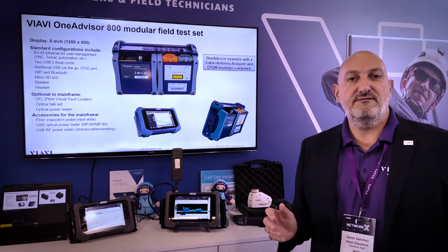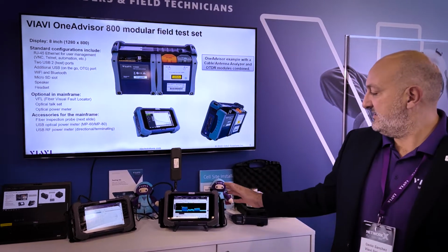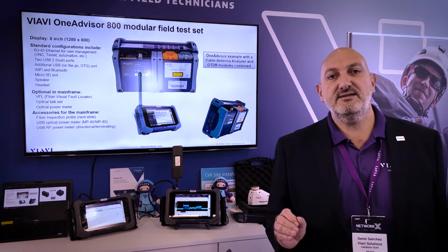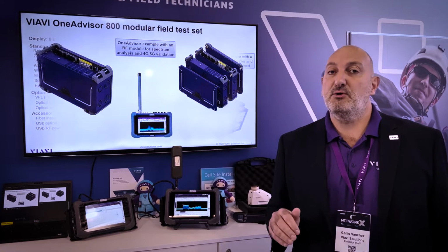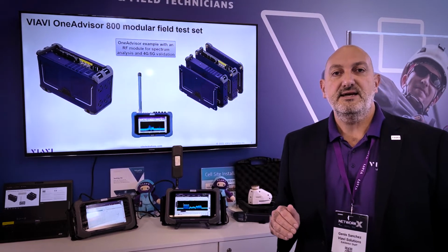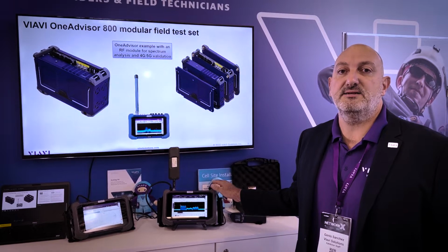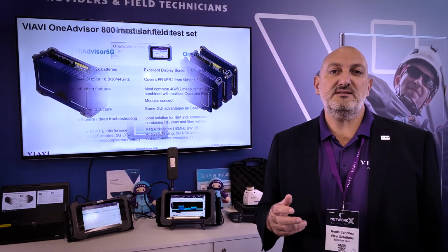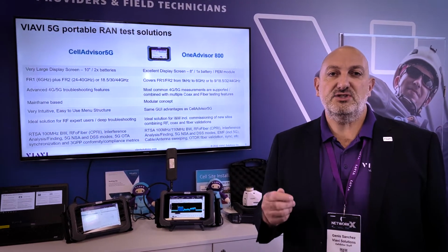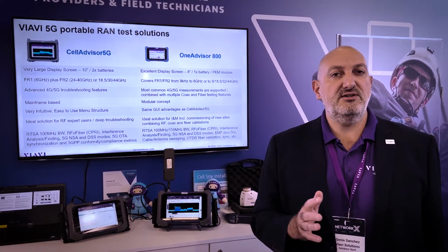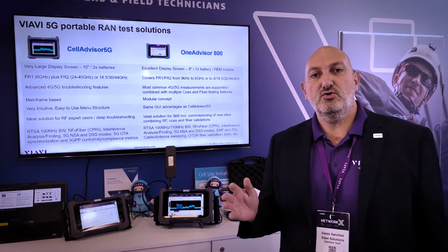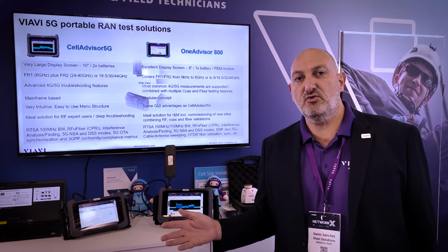For example, for external interference, the tool comes with a very neat real-time spectrum analyzer, among other interference analysis capabilities. This is a 110 megahertz analysis bandwidth real-time spectrum analyzer, and it allows you to immediately capture and identify those spurious signals, those leaks, those external interferences that are very difficult to observe otherwise with traditional tools.